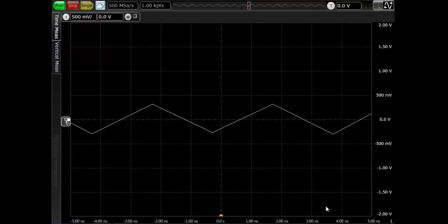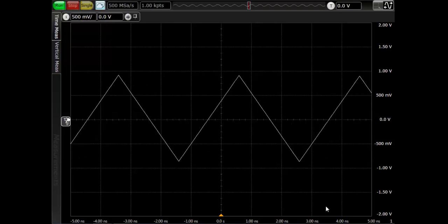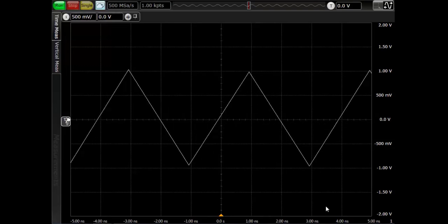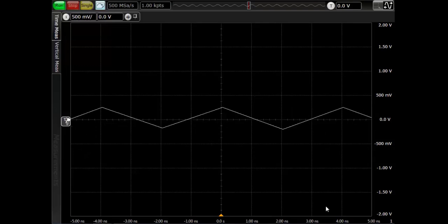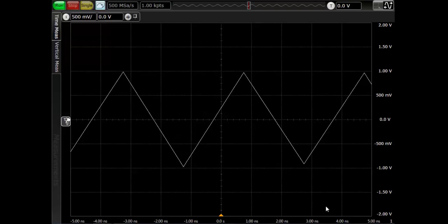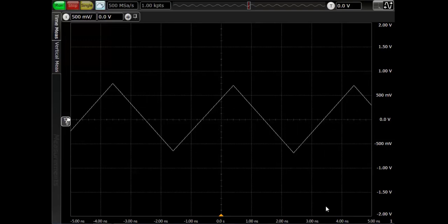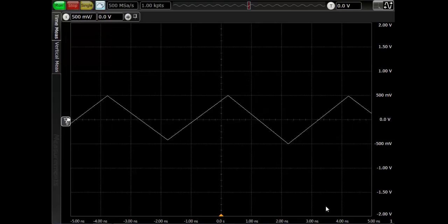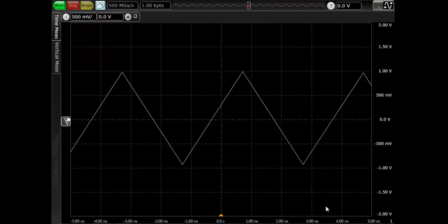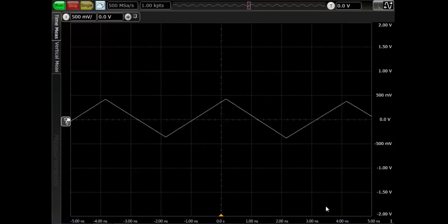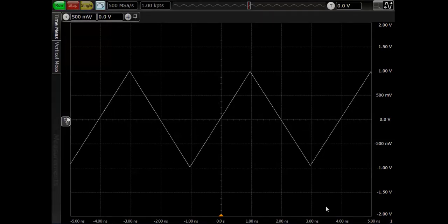This also happens with a real oscilloscope. Here we've set the sampling frequency only slightly above the Nyquist frequency, and the scope, which is sampling in real time, triggers at slightly different instants on each acquisition, so it displays a different waveform every time. The Nyquist theorem specifies the minimum sampling frequency, but reconstructing the signal also requires the application of specific interpolation formulae. Practical systems can't sample at exactly this minimum rate. As we'll see in later videos, they must sample at a higher frequency and often use sin x over x interpolation because their sampling is pulse-based.